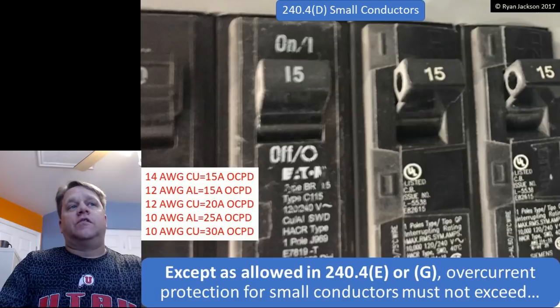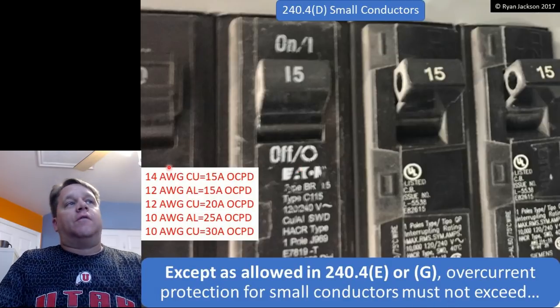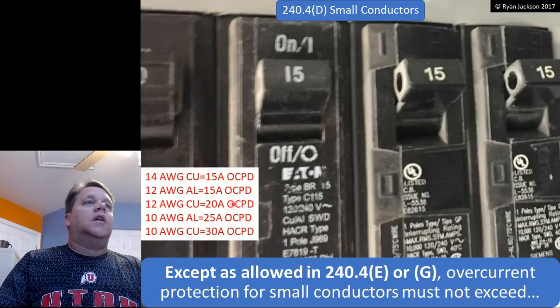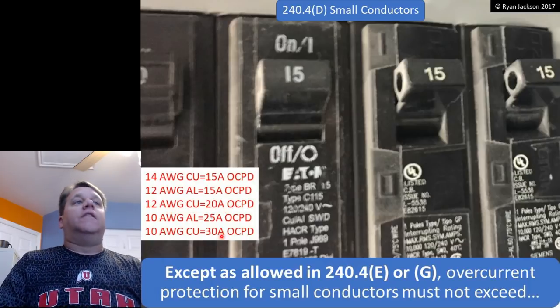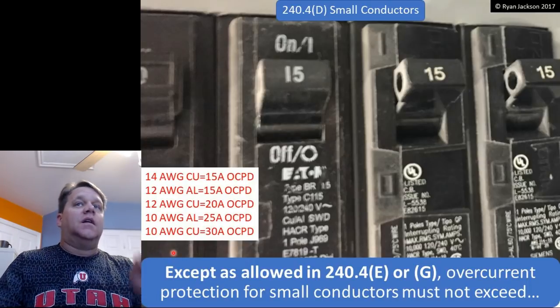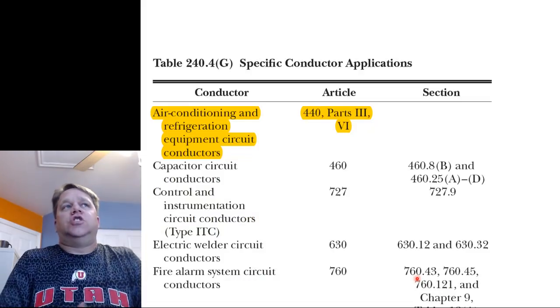Overcurrent protection for small conductors must not exceed, ultimately, for 14 gauge copper, maximum 15 amp breaker. We know that, right? 15 amp breaker, 14 gauge wire. If you got a 20 amp breaker, you got to have 12 gauge wire, copper. If you got a 30 amp breaker, you need to have 10 gauge copper, right? We know that. Now that's the general rule, except as allowed in E or G. Let's take a look at G.